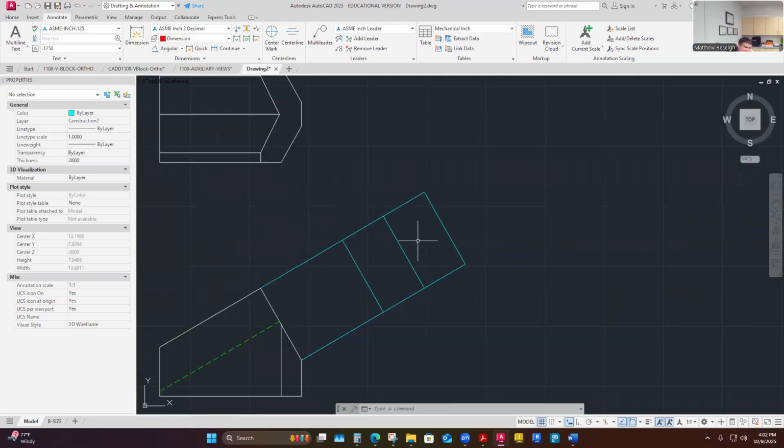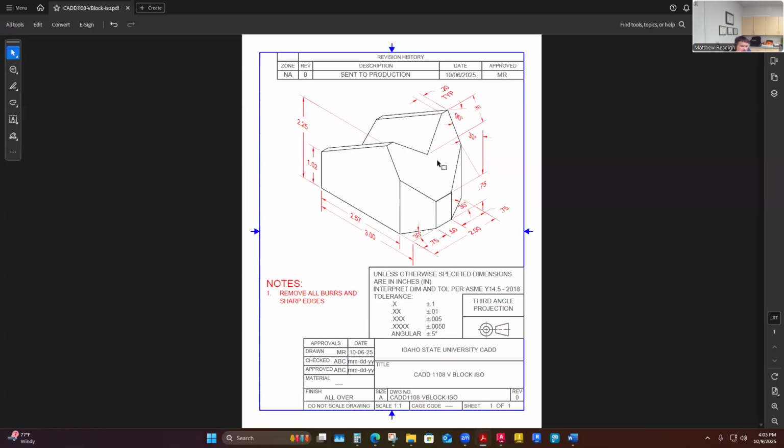But then I would piece this together almost like it was its new view, and I'm thinking about what dimensions I have to work with and what that view would look like. So I come back here and I think of myself just looking at this line. I would have this 1/2 inch dimension, and then over here I would have these dimensions, which I don't know here, but I know the length of those. They're in the front view. I could grab them. The true length is already there, so I kind of have them.